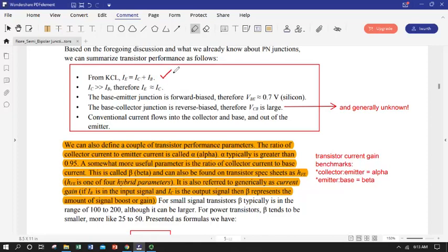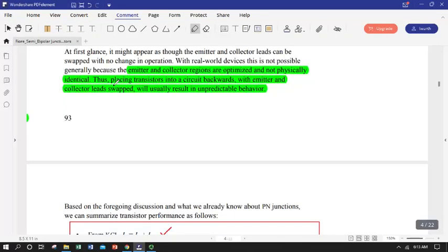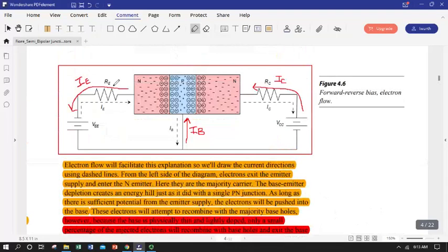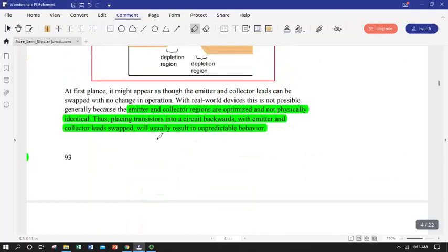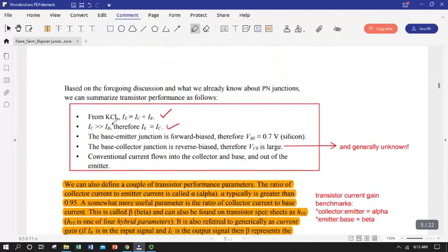And so there's rule number one. So here's rule number two. There's not a lot of base current. Remember, base current's the controller. So we have little bits of current going in the base and controlling big currents flowing through here. So base current's going to be orders of magnitude less than collector and emitter currents. Generally speaking, it's the signal. So typically collector and emitter currents are bigger, way bigger.